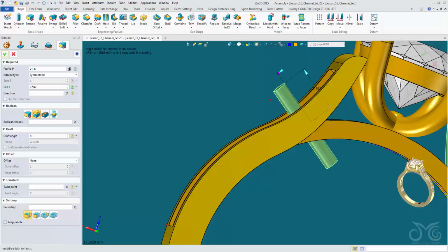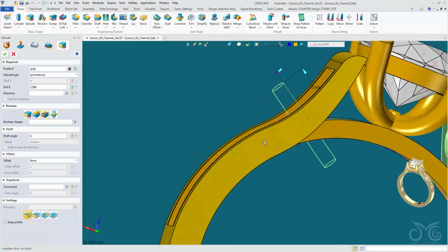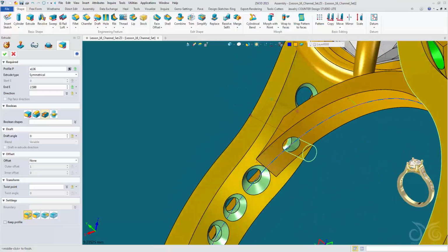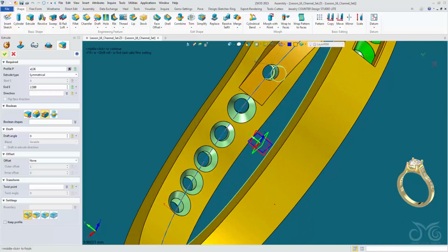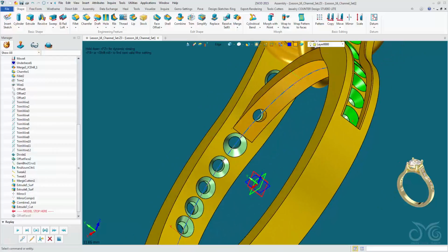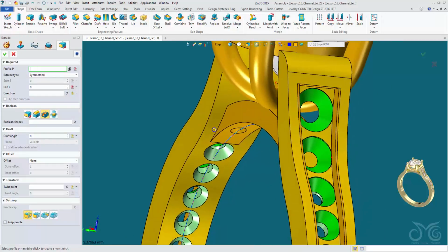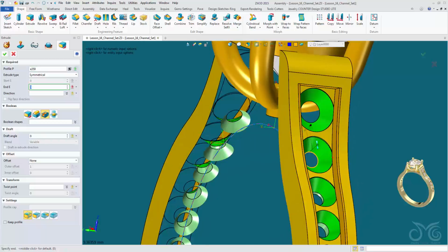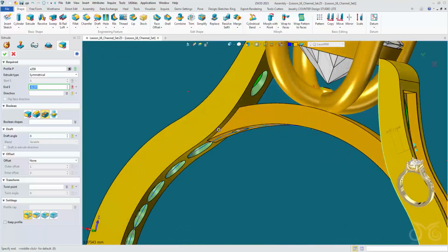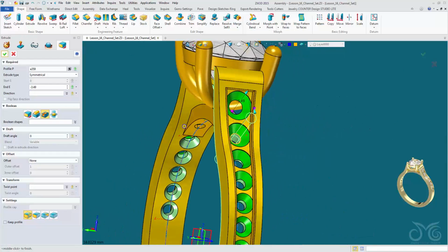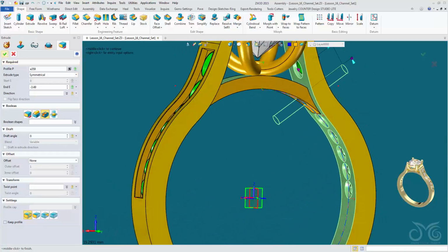That's all it needs, and we're cutting. Okay, we can specify the boolean shape we want to cut from, but it doesn't matter. Let's confirm. Middle click and repeat the operation for the opposite side. Extrude symmetrically. That's fine. Confirm.